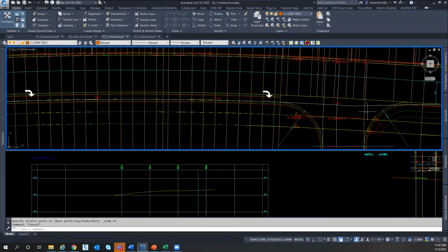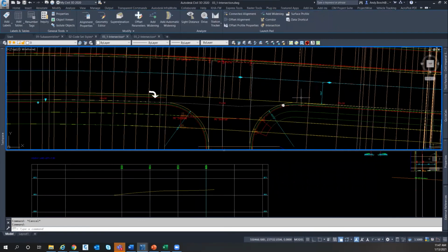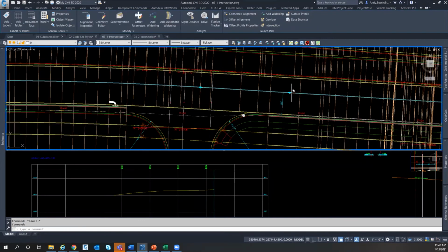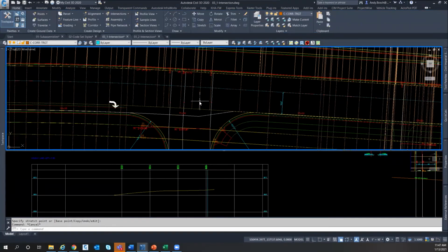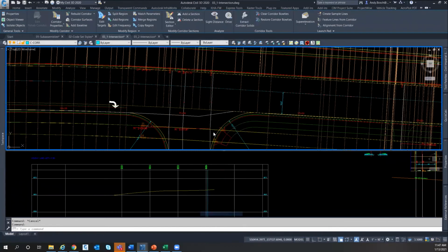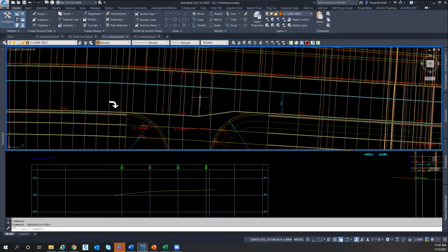And then when I go to the other side, I've got this taper happening too. This we can edit also on screen. You've got these diamonds here that will maintain that taper length, or if you click on the circle, it switches it, and you can grab the beginning or end and just slide that over. So I'm just going to slide that over. I can go ahead and hit here. I'm going to go ahead and hit rebuild. And now I've got that definition there.